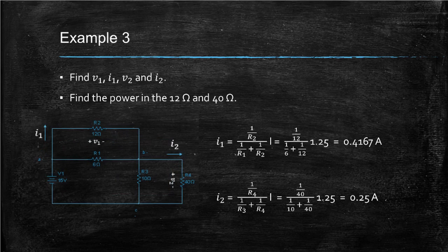Because the resistors that make up the 4 ohms resistor are the parallel combination of resistor 2 and resistor 1, the voltages are the same as the voltage of the 4 ohms resistor. Both 5 volts. We also know that the voltage in the 8 ohms resistor is 10 volts.